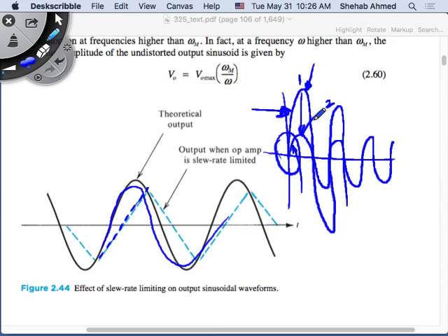For the same signal, as soon as you start being hit by the slew rate for the maximum value signal, start decreasing the magnitude. Don't decrease frequency, just decrease magnitude. If you decrease magnitude, then you become like this number 2 waveform, which has a smaller rise time. This is number 1 waveform, this is number 2 waveform. It's the same signal.